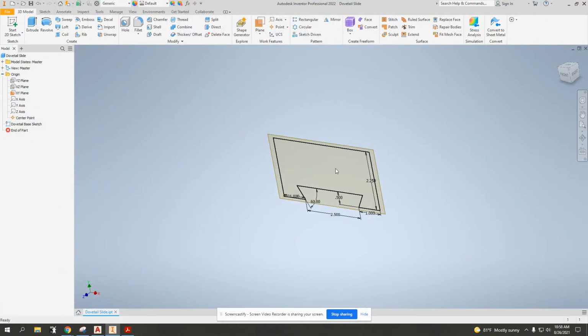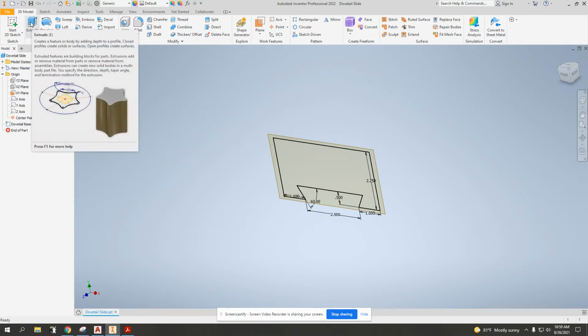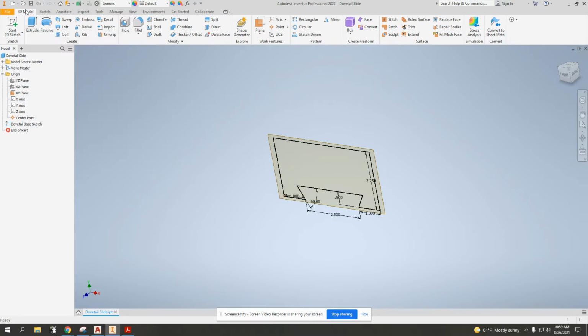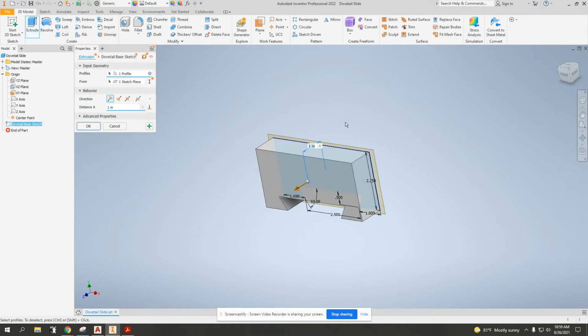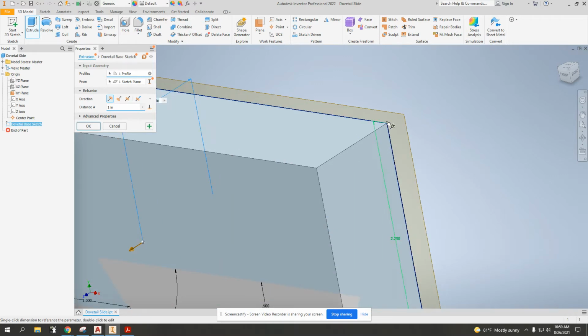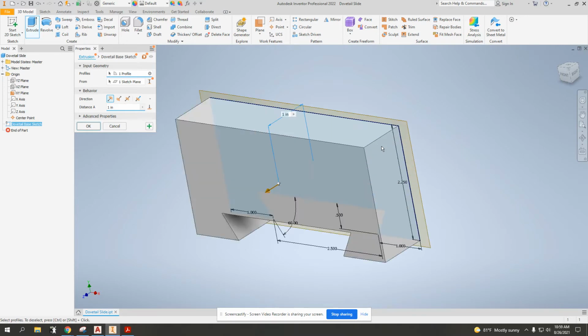Here is our object, and in this case, we want to pretend like we're back in grade school playing with silly putty, and we want to extrude some clay. Up in the top left-hand corner, we have the extrude option under the 3D model tab, and I'm going to select that extrude. In this instance, I only have one closed object, and by closed, I mean every corner of our sketch is perfectly closed. You can run into problems if they are not.